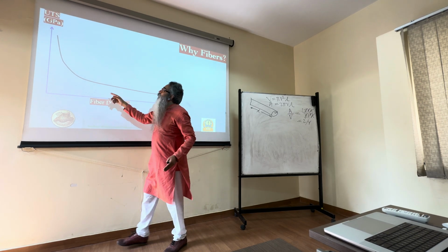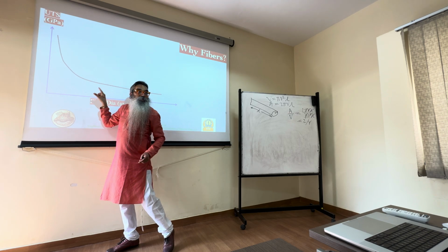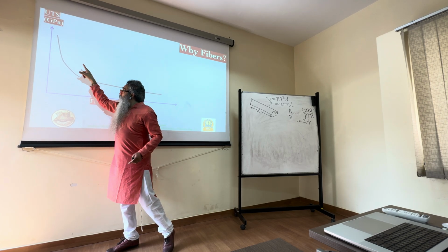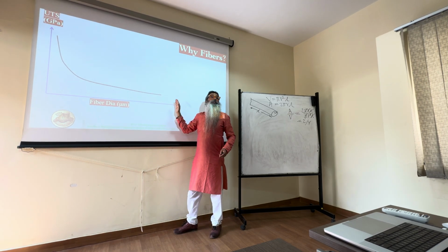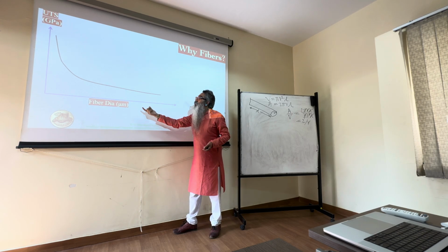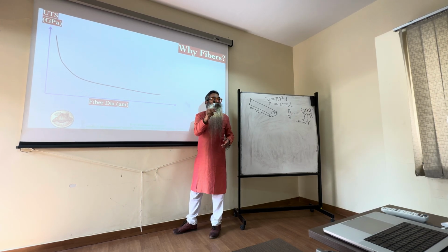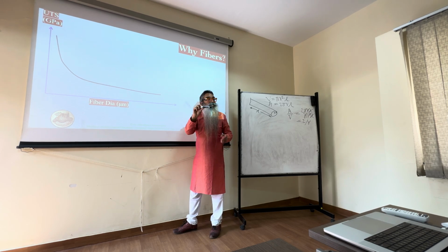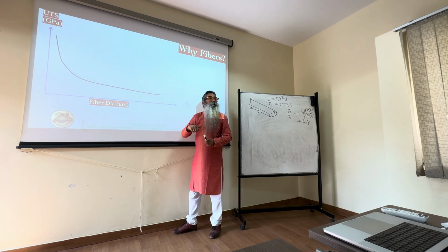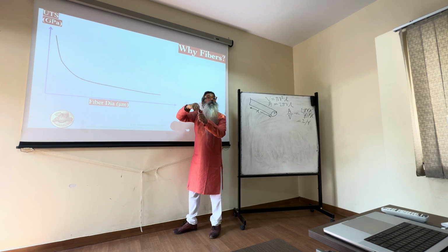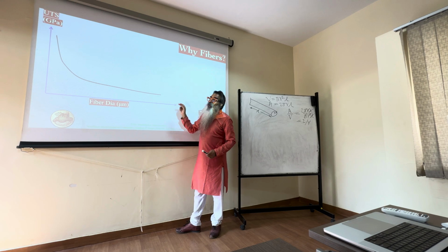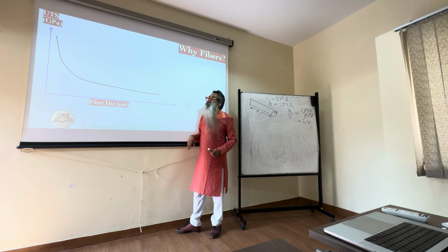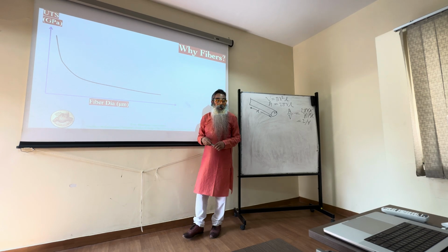If I take very small diameters, you will see a sharp drop because of a sharp increase in the surface defects, right? Whereas once you go here, you get what is known as the bulk material. You no longer have the advantage of it being a fiber geometry, okay? It just becomes a rod, right? So you're just having an axial rod which you're trying to apply tension to, and it has a certain bending stiffness now. It has other kinds of applications, but it does not bode well purely for a tensile application because the stress at which it fails has come down so drastically, right?